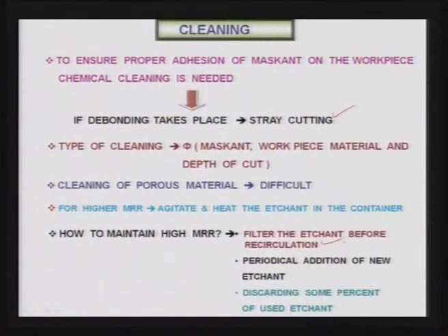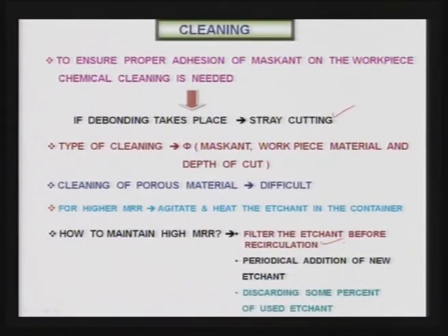Periodical addition of new agent is needed, because the etchant is always getting mixed with the reaction products. So, it is desirable that after a certain period of time, say 25% of the old agent is taken out and 25% new agent is added. That will keep maintaining the strength of the agent, so that the material removal rate does not go down, discarding some percent of used agent.